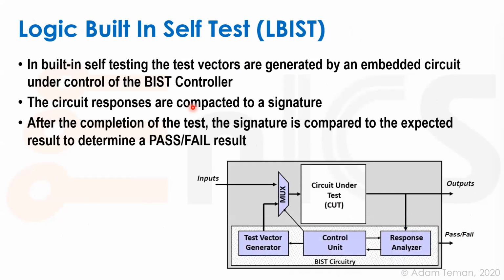There's also logic BIST. So logic BIST is again making a BIST, but not for a memory, but for some sort of logic circuit. And it's harder to do than memory, but it's something that is more and more common because the hardware that you have to put into the chip is often much cheaper than the testing that you have to run on the chip. So you try to do some sort of logic BIST with the LFSRs and different things that we showed before.